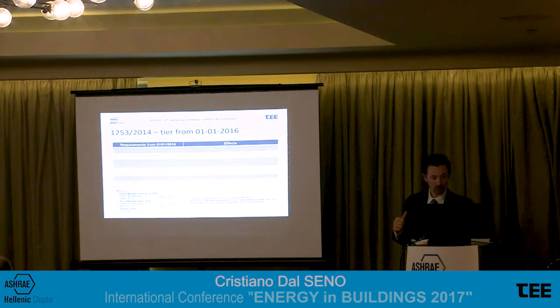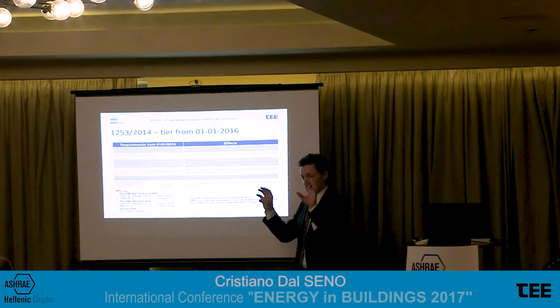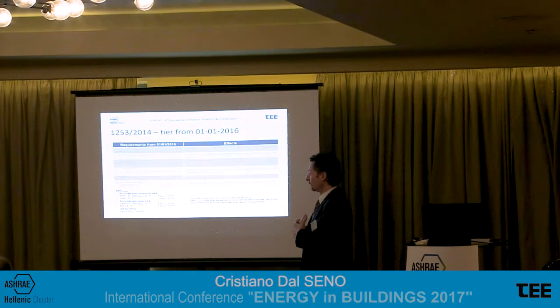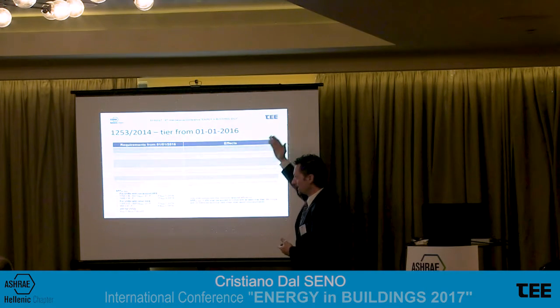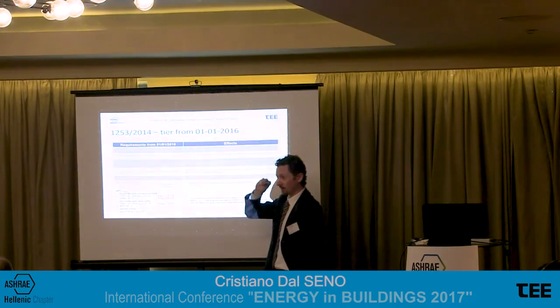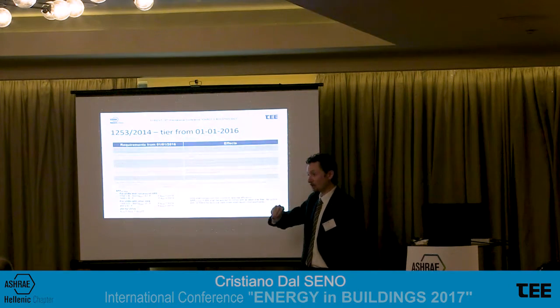If we go to bidirectional ventilation units, so we have supply and exhaust fan, and we must put a plated exchanger or a recovery wheel in between to recover energy, things become more complex. So we have this incredible list of formulas we must apply. We consider the specific fan power, which is the reference value, so the electrical energy the fan uses to move 1 cubic meter.